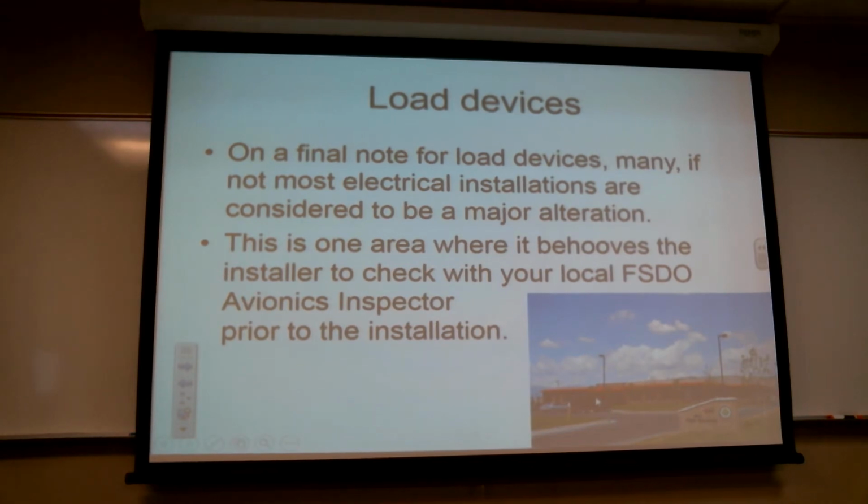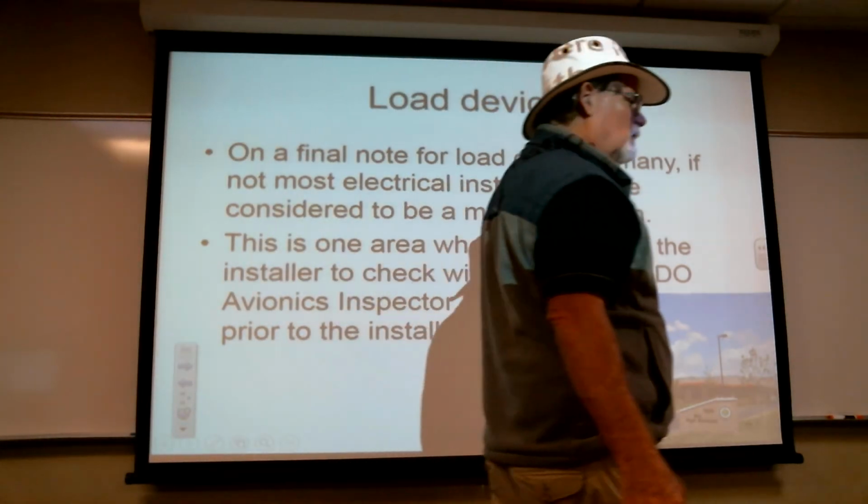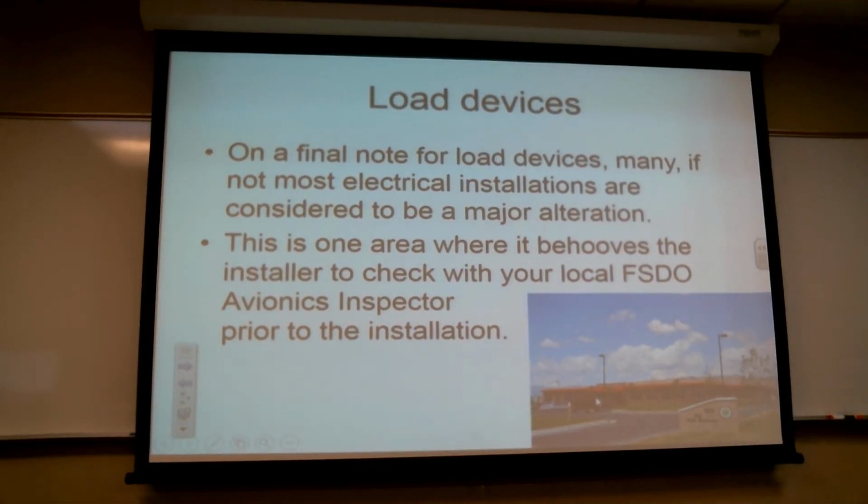And the definition of whether it is a major alteration or not is somewhat subject to the local FAA inspector. I've talked to a lot of inspectors over the years. I've seen some of them be so anal as to say, if it's a suction cup and it's plugged in with a cigarette lighter, it's a major alteration. That's a little over the top. You know, certainly if you're going to be cutting, hacking, crimping, connecting wires, all of that kind of stuff, there's a pretty good likelihood that most inspectors are going to consider it to be a major alteration.